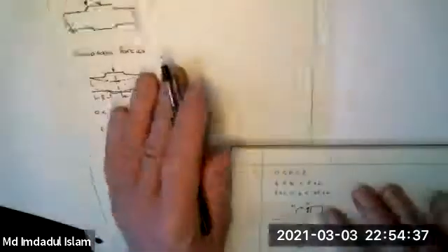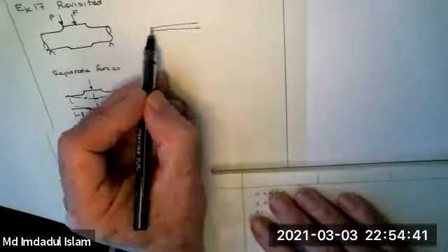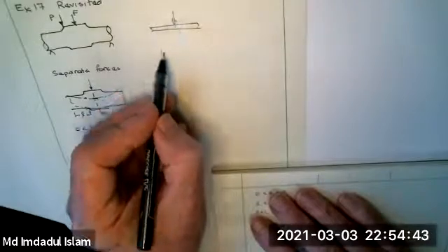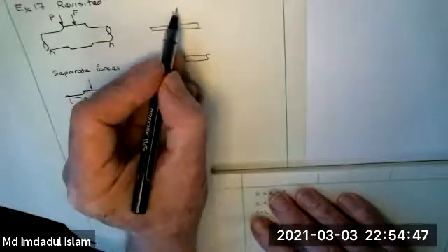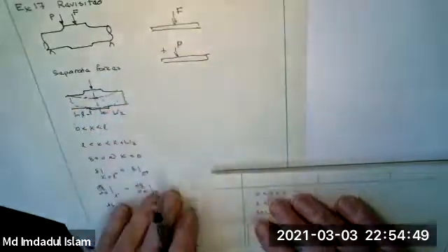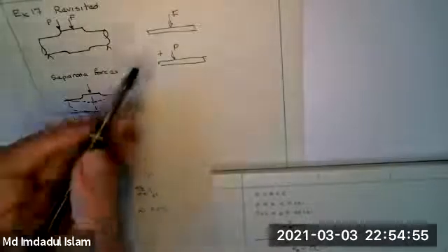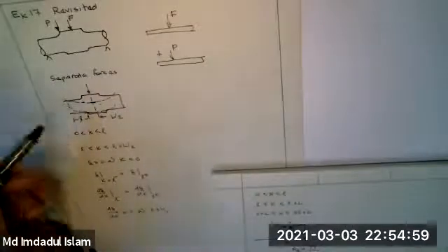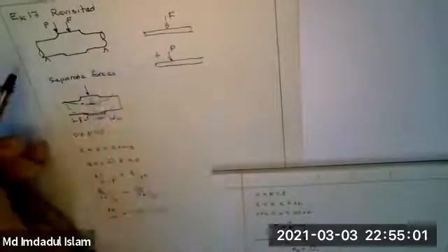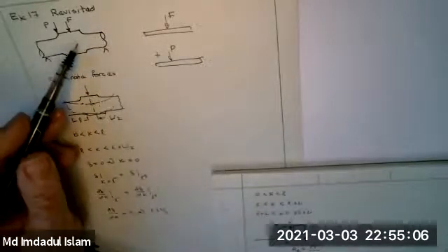So I said this is equal to, I'm just going to sketch the beam as a straight line, that plus that. Okay. And by doing them separately, they become easier problems. The first one's symmetric, and as I said, that happens quite often. You only have to do half of it, so that makes it simpler. But even the P problem is simpler. Even the P problem, you now have 1, 2, 3 regions instead of 1, 2, 3, 4.